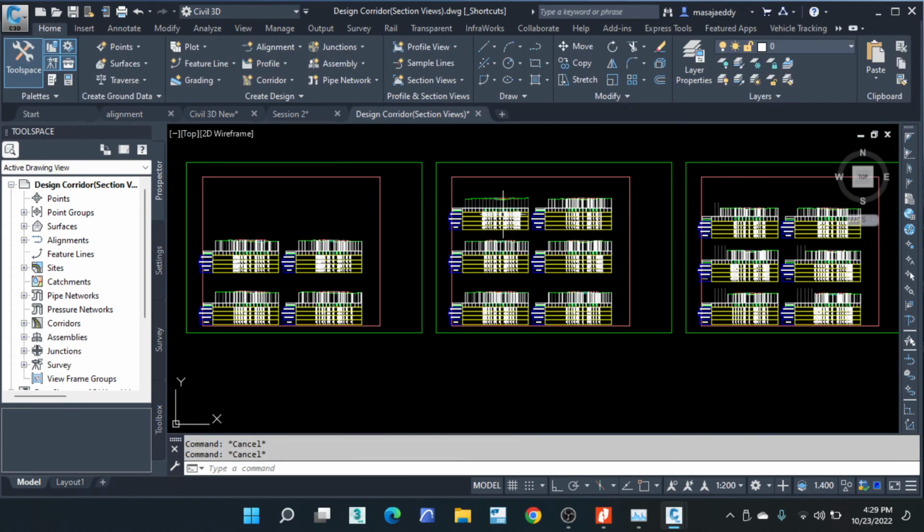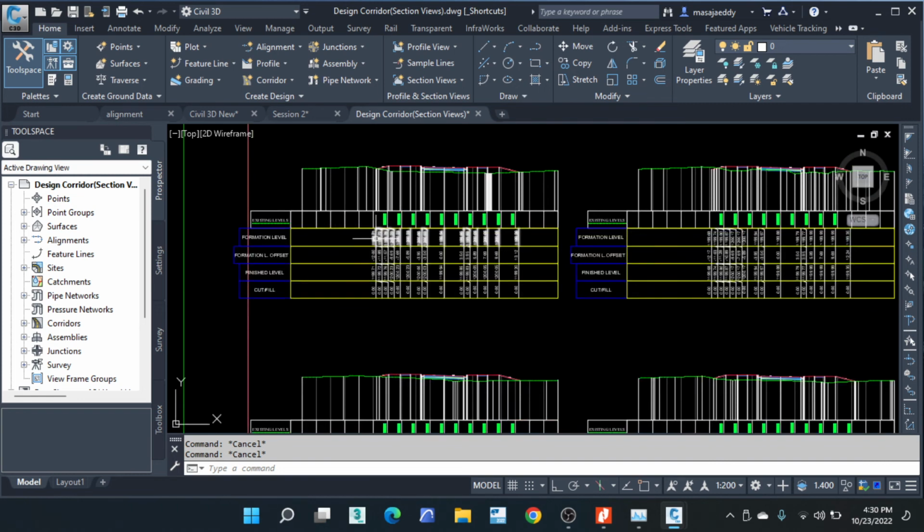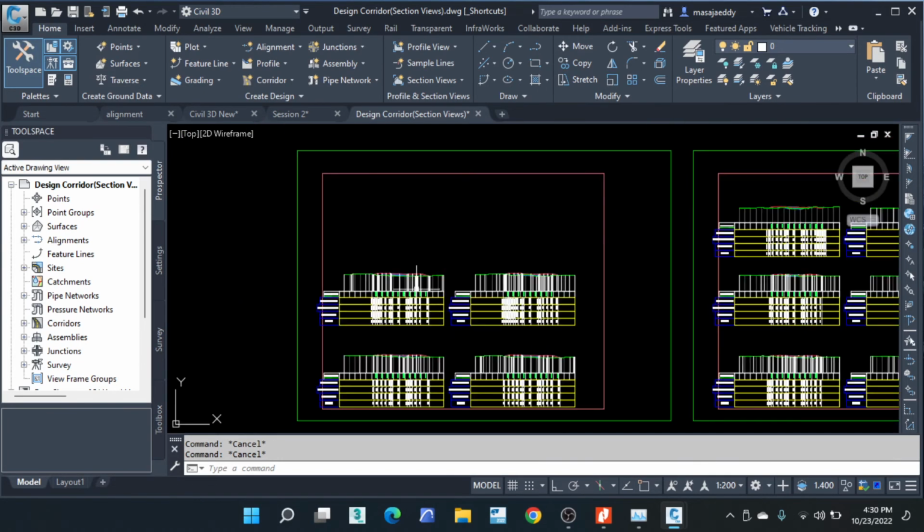So sometimes it can be helpful. You can edit one section. Then you delete that section when you've saved your styles and also your band set. When you're now reproducing the sections at all the ranges, at the chain edges, you just come and bring the band set once and for all, so that the sections will be formed when the band sets are already there. Okay? Yeah. So let's move to materials. Any question before I continue? We are clear? Okay. So let's move on to materials.